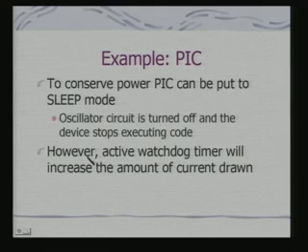However, an active watchdog timer will increase the amount of current drawn. If the watchdog timer is on and it is monitoring, it will continue to draw current. And in fact, you can have timers which may be driven by external clocks, which can be used for operations even when the processor is in sleep mode. So, this is a very simple architecture where you have identified only sleep mode to conserve power for the processor.